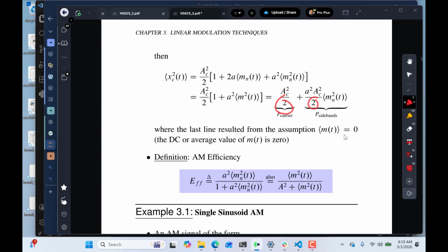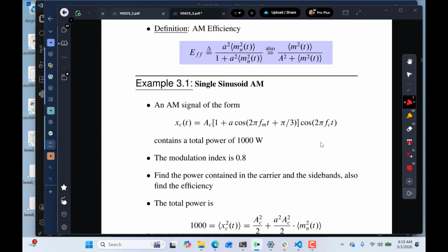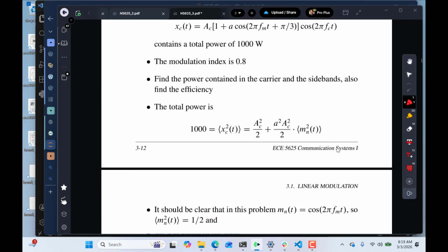It's not super complex. When we go up into FM modulation, though, FM does not make the amplitude of the signal rise and fall with the message. Instead, it's changing the frequency or the phase. So the carrier signal can be a constant envelope, but what's going on is inside the argument. So it's the waveform itself, it's frequency shifting it or phase shifting it. Different character and different behaviors. Single sinusoid, we looked at that last time.